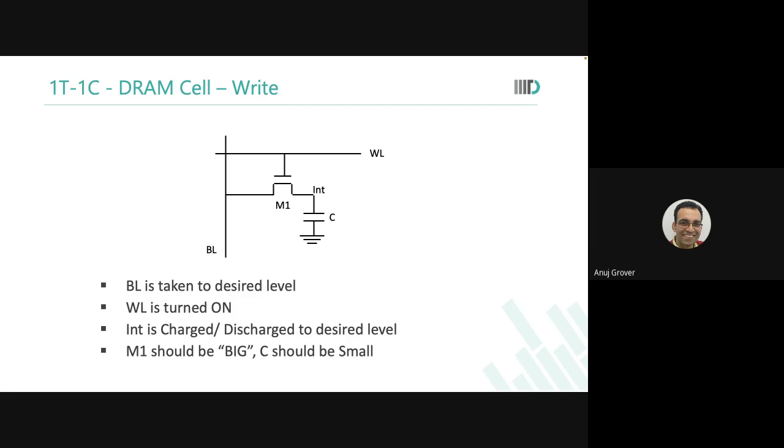So scaling, you will realize, we saw in SRAMs, scaling is an issue. When you are starting with DRAMs, I'm telling you again, scaling is an issue. We will go to flash, and I will tell you again, scaling is an issue. And that is the reason why there is a very strong push for emerging memories which are not storing data on the basis of charge. SRAMs, DRAMs, flash, all of them are charge-based memories.